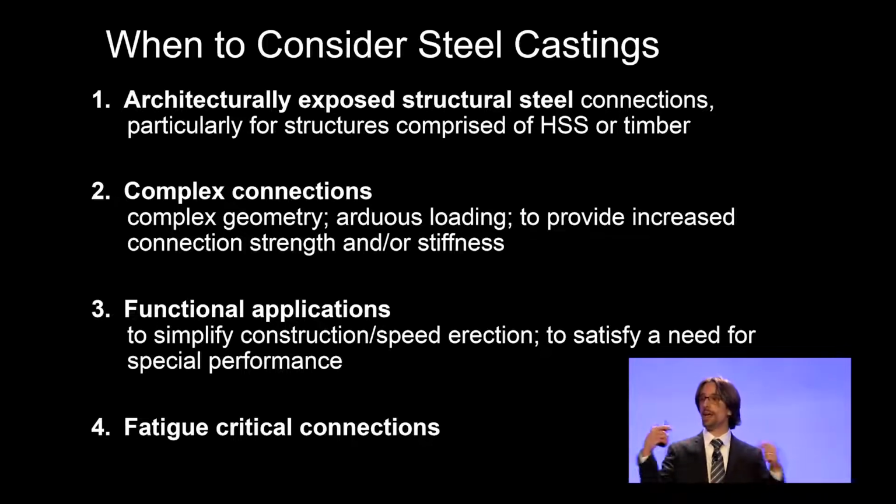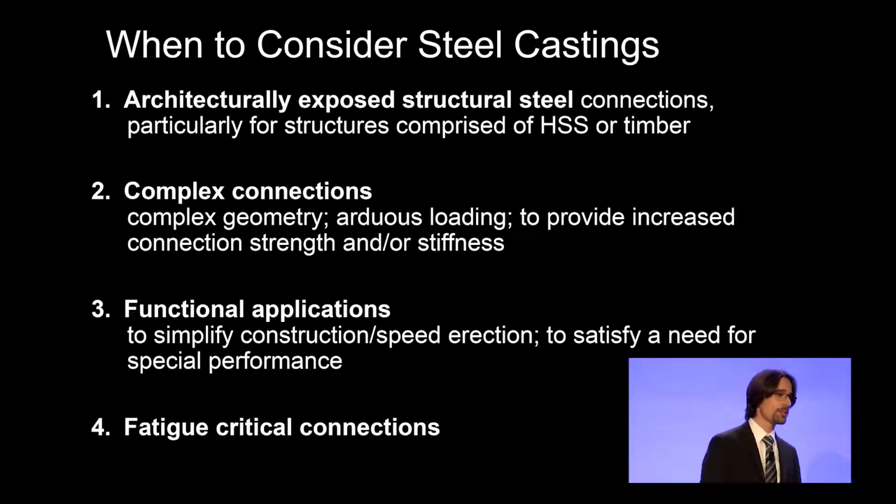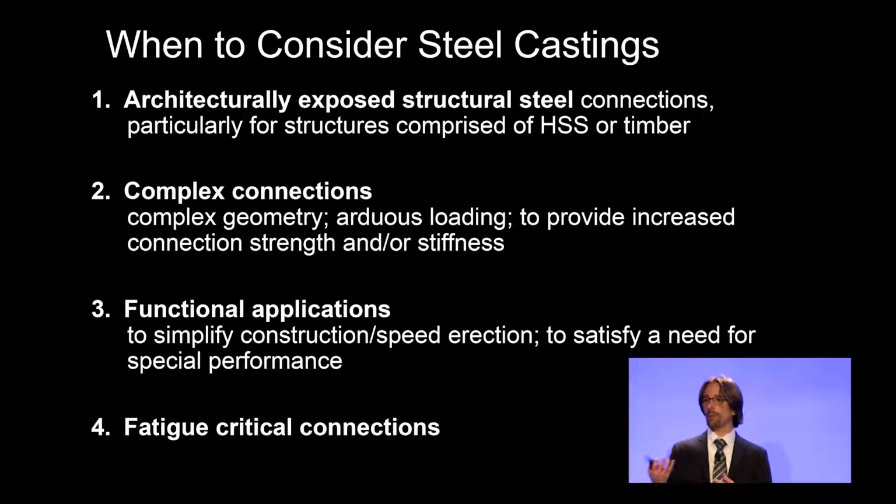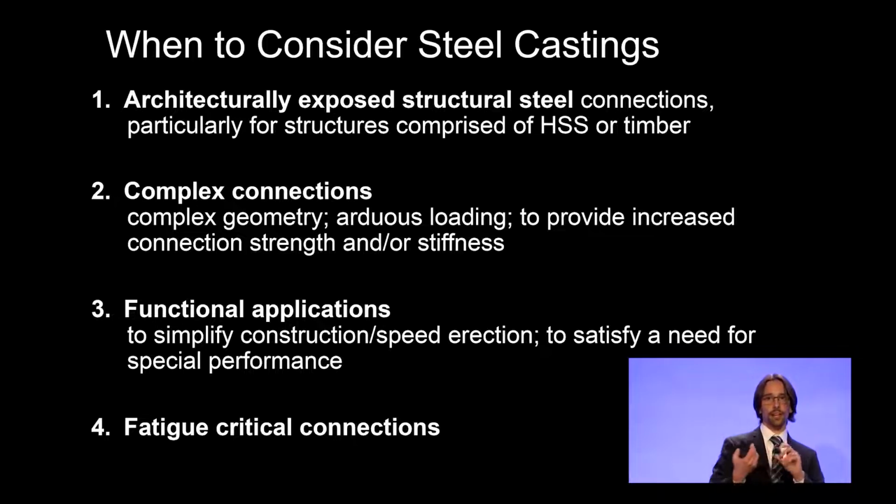Complex connections where you have many members framing together, where the connection has to carry very arduous loading, high seismic applications, for example. Functional applications where we can leverage the geometric freedom of castings to address other constructional constraints. So for example, if we want to use a bolted connection to simplify construction, we can transition a structural member in an elegant way and maybe reduce construction costs. So there's an opportunity there to leverage castings.